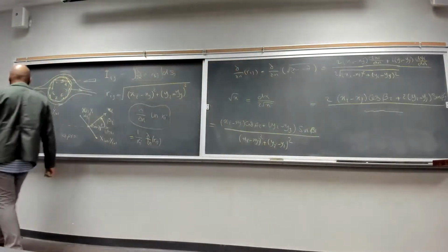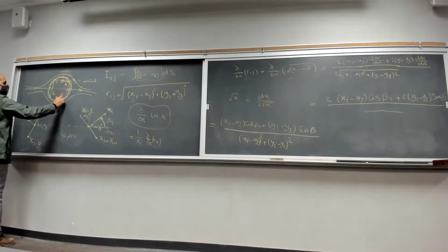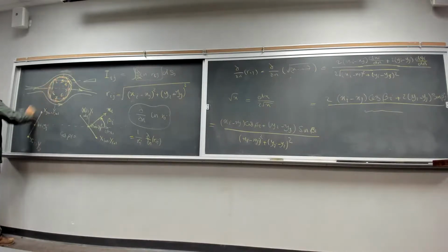What it means essentially is we are going to get 8 pressure coefficients for 8 points on the cylinder. But we already have the distribution all over the cylinder. If they match up with the distribution we already have, we essentially have a very good result, right? And you do it for 4 panels and then compare the 4-panel results, which will give you only 4 pressure coefficients, because you only have 4 panels. Compare it to the 8 results you already have, and then compare to the analytical solution.